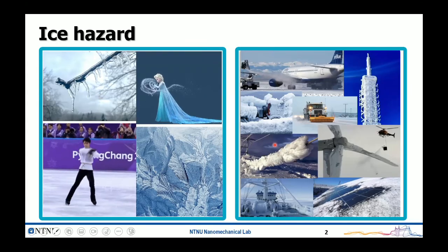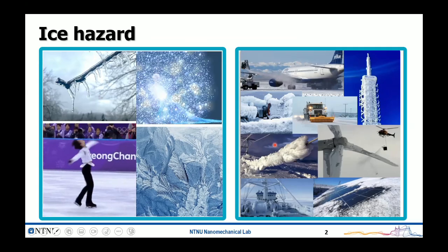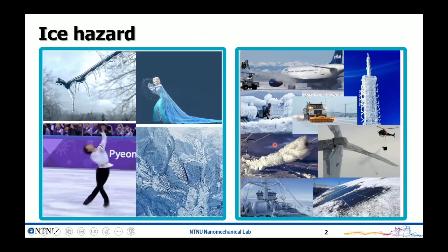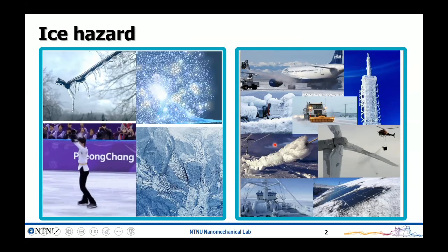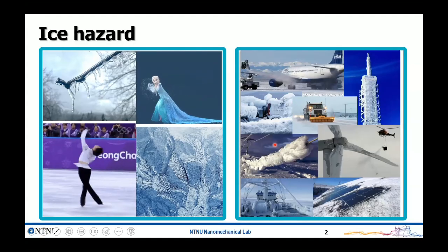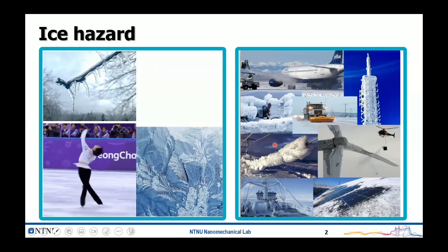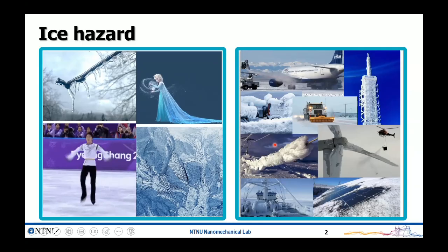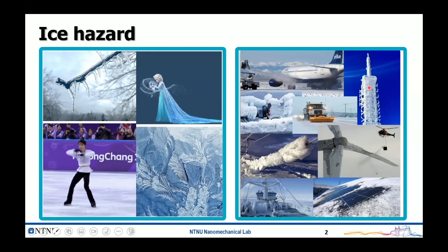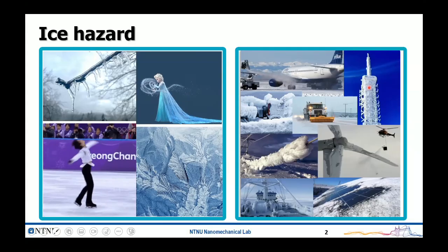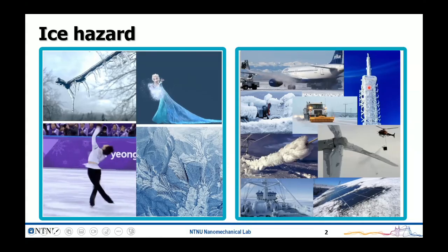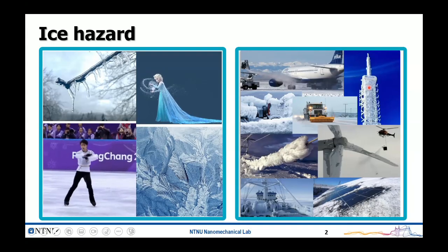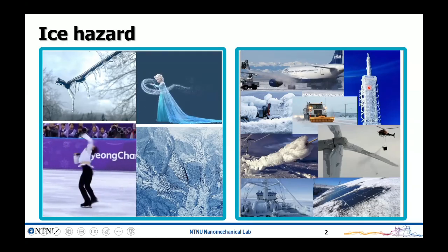In 1969, due to the icing problem in Norway, 1 meter of power cable accumulated 359 kilograms of ice. The consequence is that it collapsed the whole power cable and the tower. It took almost 2 months to fix all the problems. And also the signal towers for mobile or other signals: when there is ice, due to the different dielectric constant, the signal reduction can be up to 90%. So it really influences our daily life.